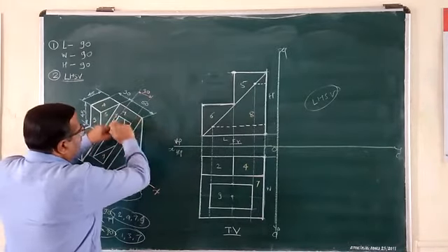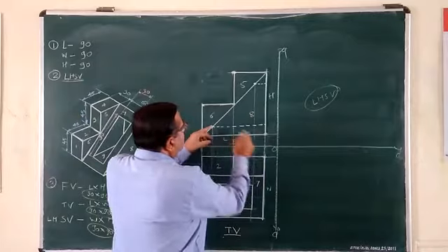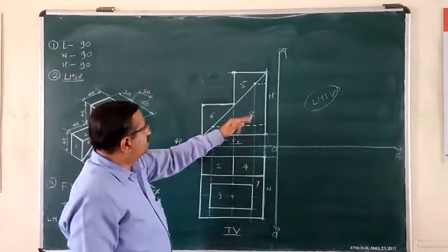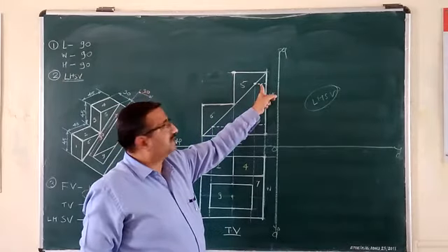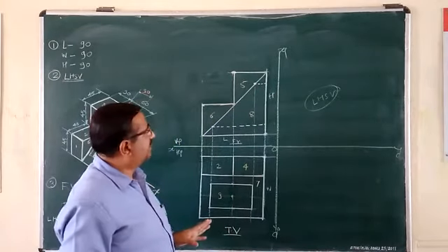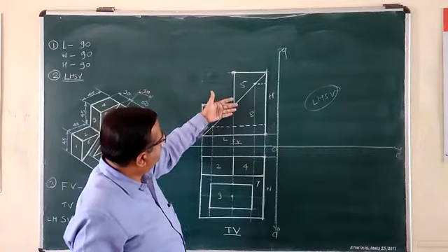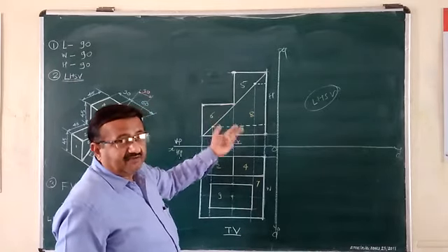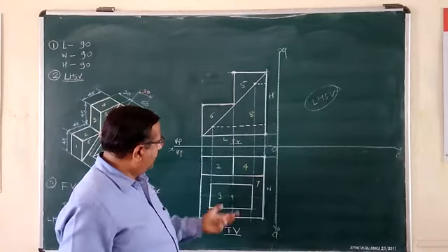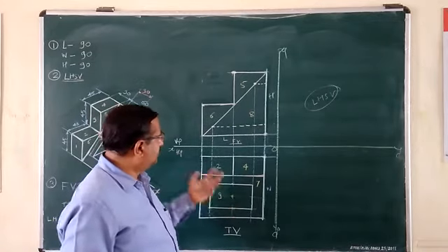Similarly, these two are also getting overlapped. So this single dotted line is reflecting the bottom corners and the top corners of this hole are represented by these dashed and thick lines. Okay, so this completes your front view with thick as well as dotted lines, with visible as well as invisible effect. And here only visible things we have shown.